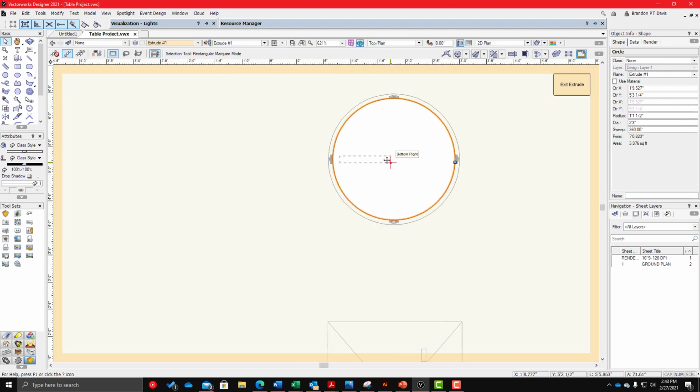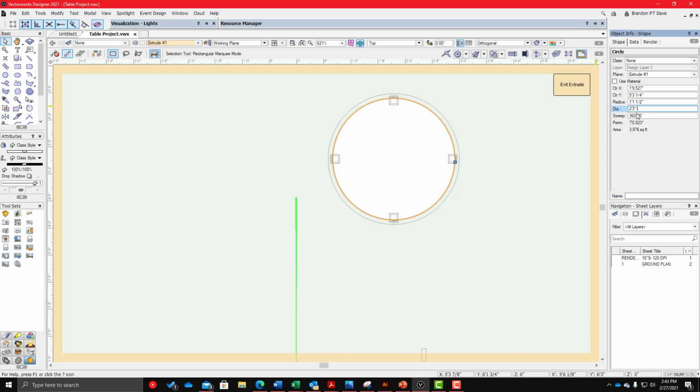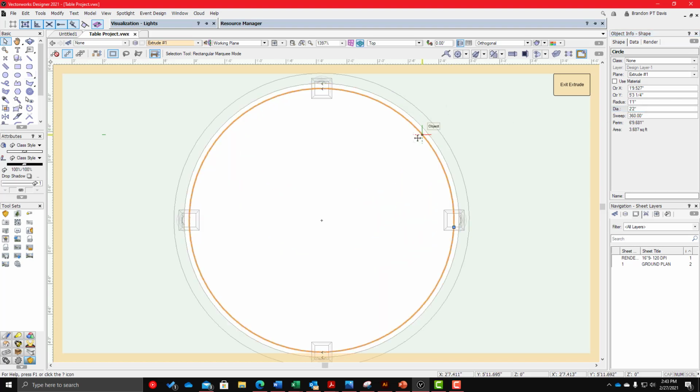You know, if I wanted to be concerned, I guess what I could do is go back in the top plan view. I could duplicate or offset. I'm going to just duplicate it, subtract 1 inch. Whoop. Did not duplicate that. So I'm holding control and then one click to duplicate. Hit subtract 1 inch. So now it's, you know, 1.5 inches. Sorry, 1/2 inch off all sides.